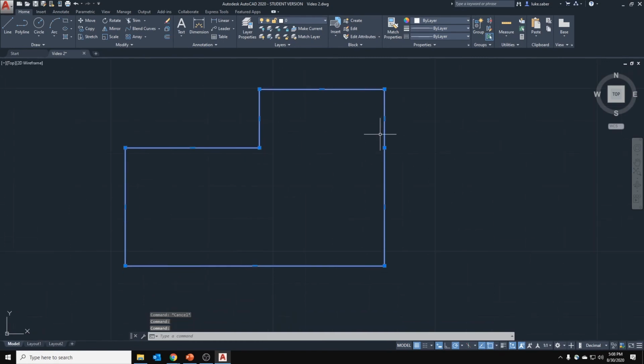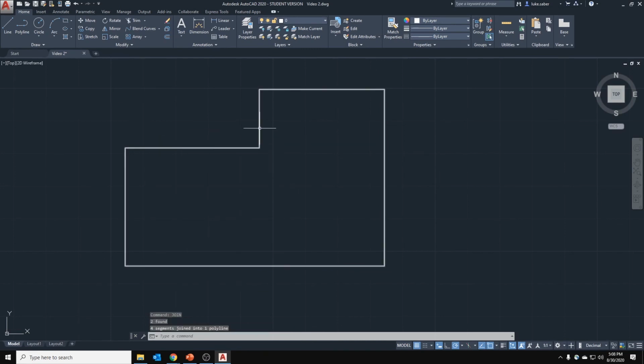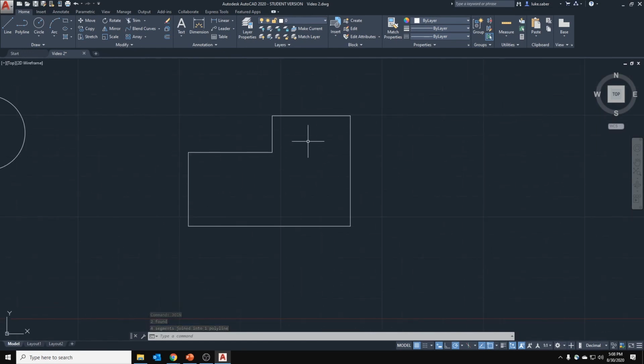One big thing, because you can't stretch things that aren't connected, right? Because then you're just moving them. So let's take all of this and use join. Okay, so a pretty practical thing is the way that it works is it's similar to move copy, where you have an initial point, final point, and it's connected by a line defined by an angle and a distance. May need to rewatch that.